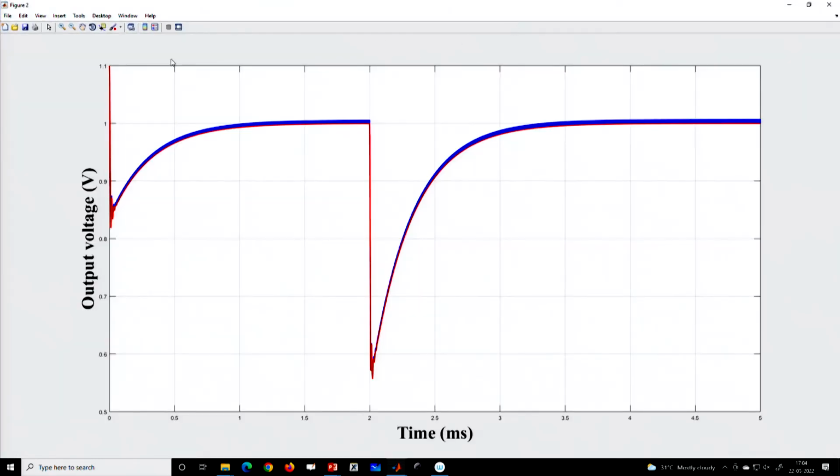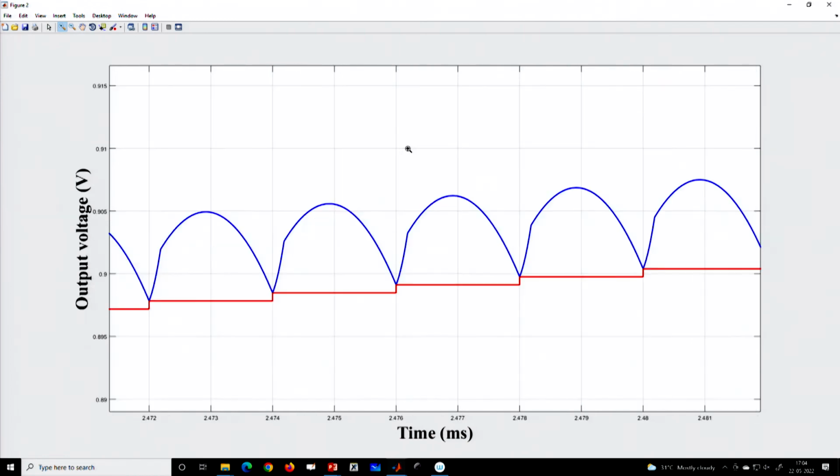First I want to show the output voltage waveform. Here I am not showing any delayed version of the output voltage, because if you add delay, you can customize it based on the requirement, but I want to first show the basic implementation of fully digital current mode control, where there is no need to consider delay. So, you can assume that the output voltage is sampled exactly at the switching point or just before that, because if you go to delay, there will be more advanced analysis, which will be very complicated and is actually a research topic.